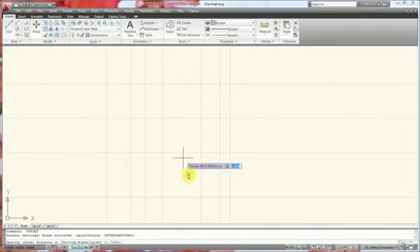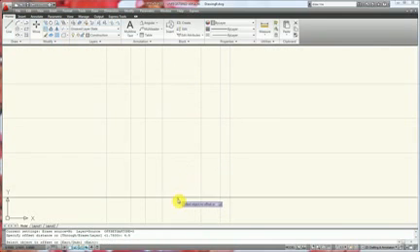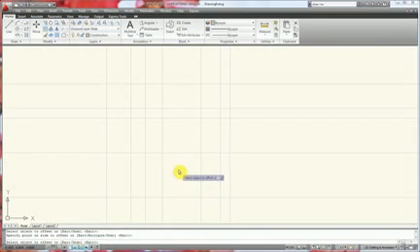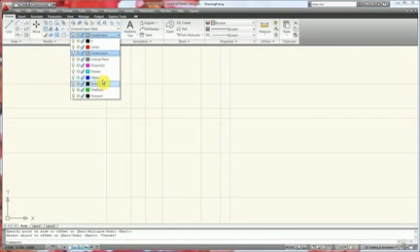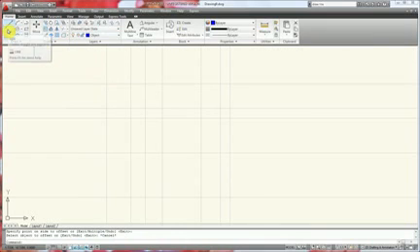And then go up 4.5. Okay, those should be all the construction lines that we need to construct this. Next thing we want to do is go to our object layer and basically start connecting the dots of all the intersection points here.